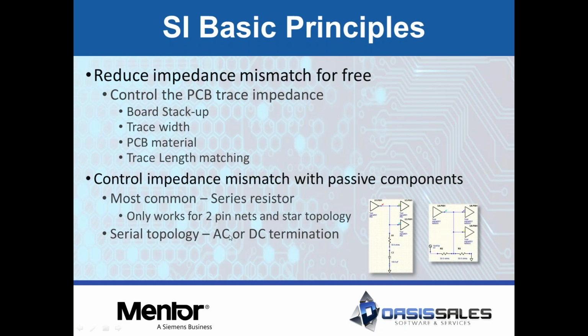These ones obviously have more parts involved. Some of them can be power consumption heavy. You got to be careful with DC termination. If anyone's done any DDR1 or 2 designs of the old, that was the number one way when using DIMM sockets, was to use a DC terminator at the end on a multi-drop net to assist with termination. Most DDR devices now have changed these days. The 3, 4 devices really don't require that anymore. But there's other concerns that happen because the signals are switching so much faster than previously. So keep this in mind.